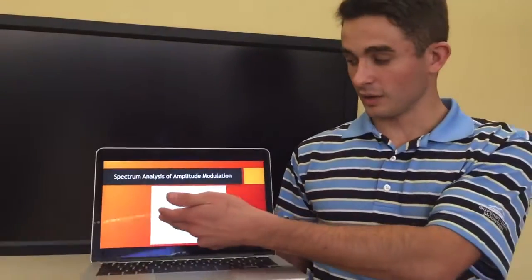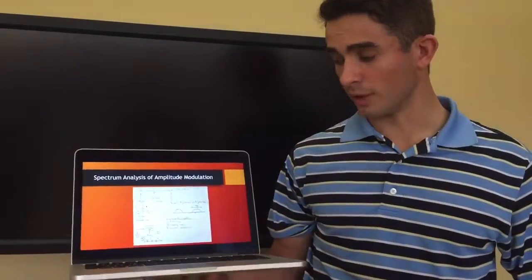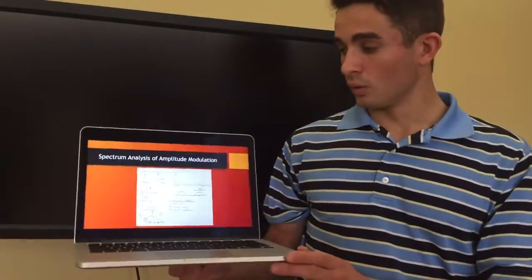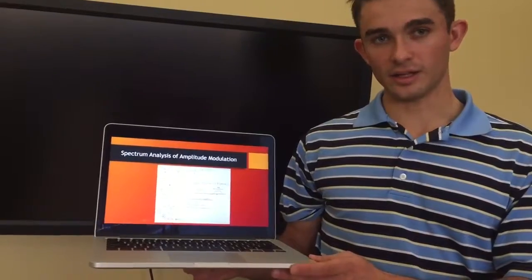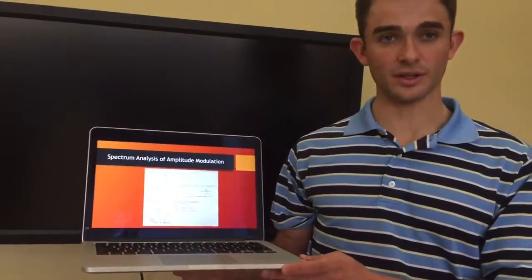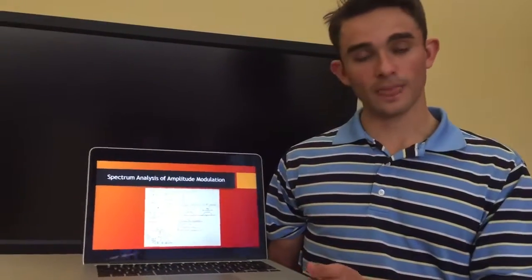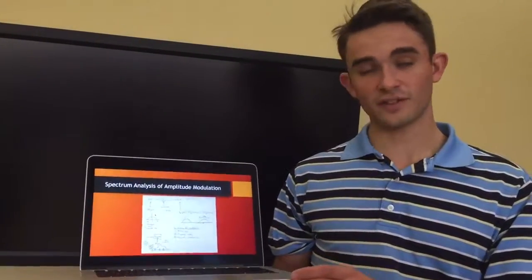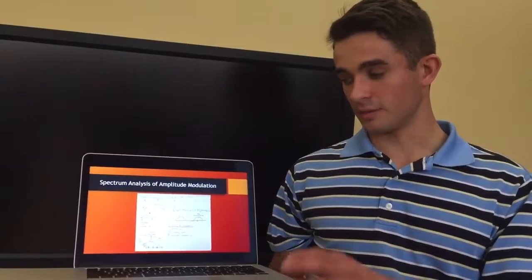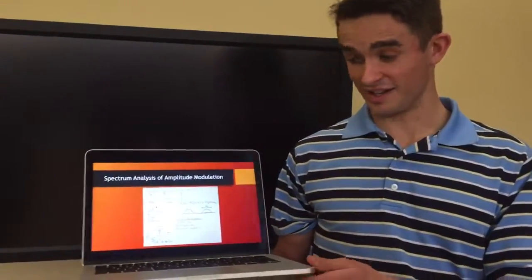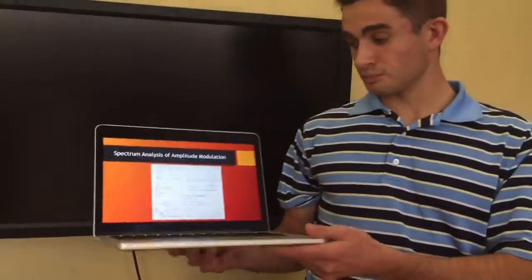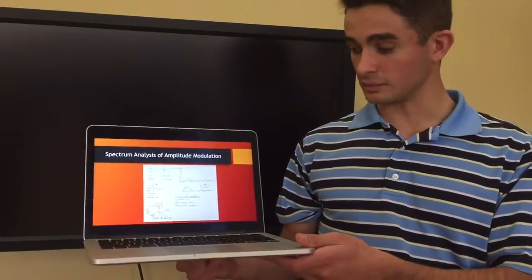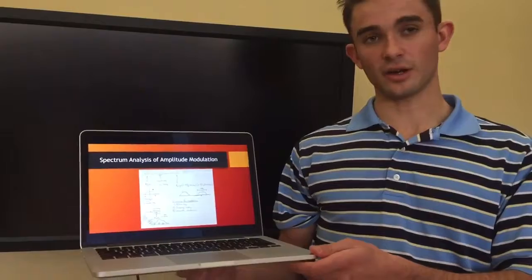So what we can see here is an arbitrary baseband signal, which is our voice, with this spectrum. And we have a cosine omega naught t. The spectrum of cosine omega naught t is just two deltas. So when you convolve our analog signal with our local oscillator, you get two shifted versions of our baseband signal shifted by omega naught, and our omega naught is 900 megahertz. This allows us to transport the signal at 900 megahertz, and our signal is essentially encoded within that cosine.